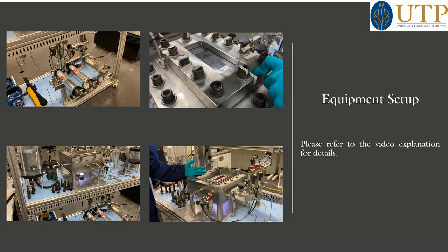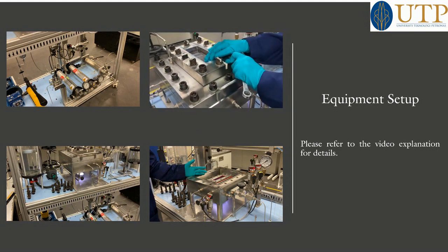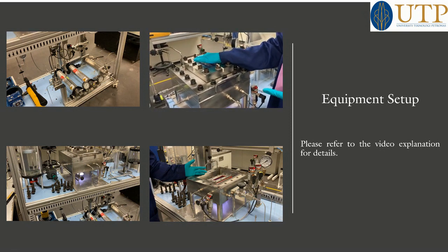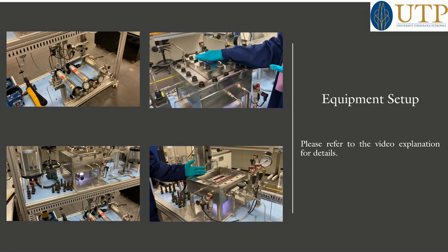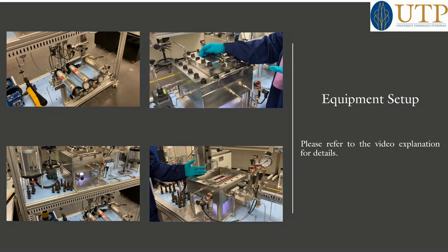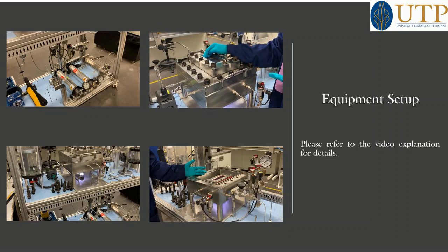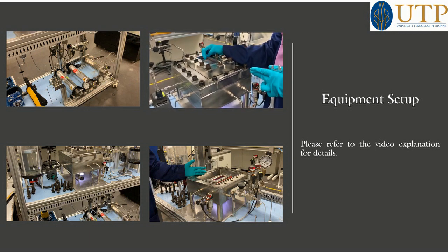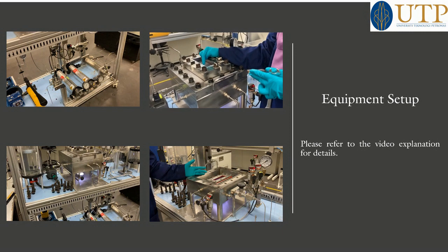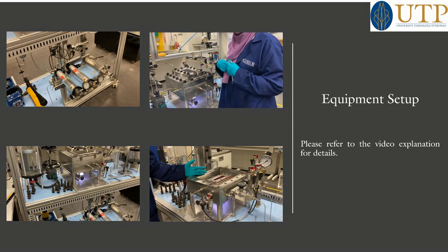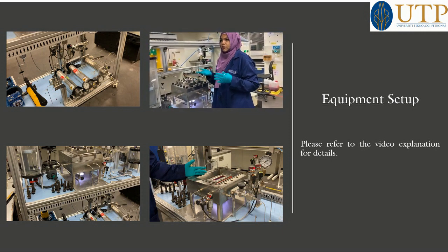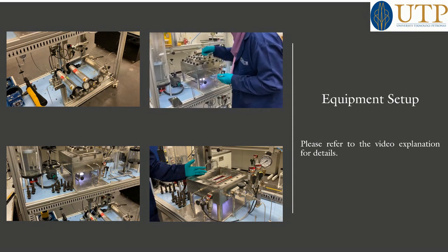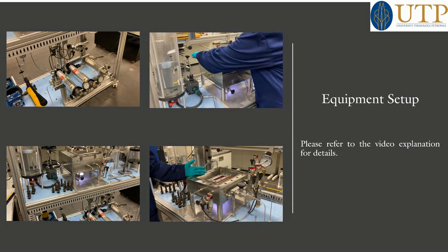So basically why are we using water to fill this up? The first thing is to get the proper visualization. It's easy to get the proper visualization through water. And secondly, if anything happened inside the micromodel, then this water will prevent the excessive sudden pressure difference or anything. So for this one we use water. So when the water is already flushed, now open it.